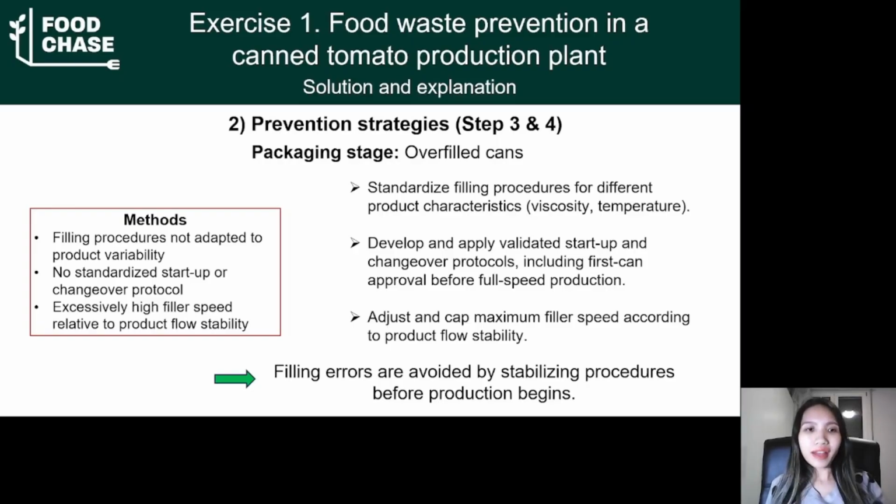If there's no standardized startup or changeover protocol, we can develop one, including first scan approval before full speed production. Then, for excessively high fill speed relative to product flow stability, we can adjust and cap maximum fill speed according to product flow stability. In this way, the filling errors are avoided by stabilizing the process before production begins.